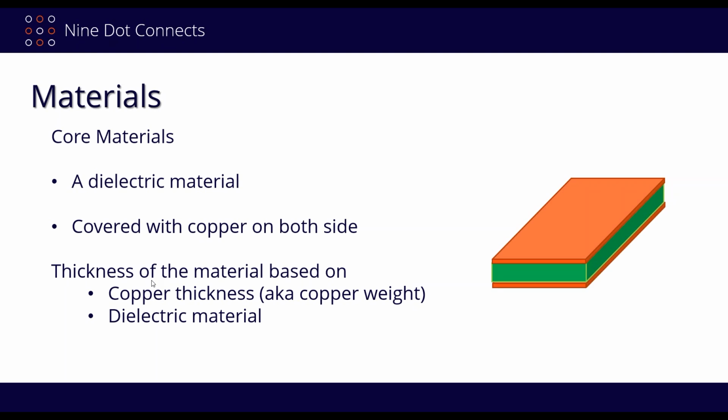If you look up FR4, you're going to find dozens of different materials out there, and many of them have to do with the different sizes and weights. When I talk about size, I'm talking about thicknesses. So different thicknesses of the prepreg, or pardon me, in this case, the core, and also the top and the bottom copper as well. So when you look at it, you'll see a bunch of these things being listed.